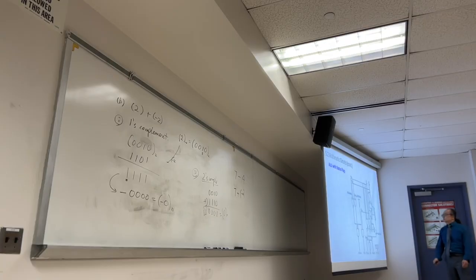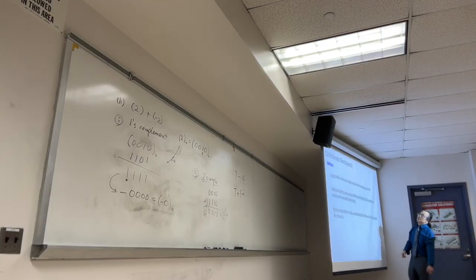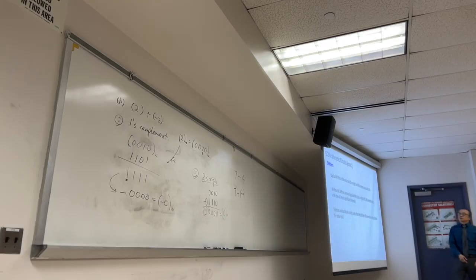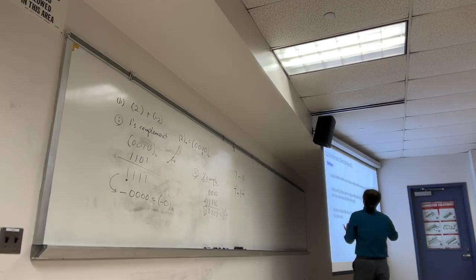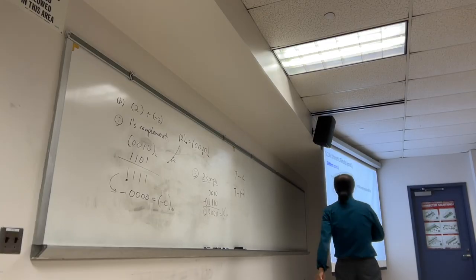Okay. So this is the whole ALU with everything. You don't have to worry too much about the components, but you need to understand what's going on with the N value, Z value, C value, V, and so on. Shifters, this is important, right? So logical shift to the left fills the empty space with a 0. Arithmetic shift is a different story, and we have a rotator as well.